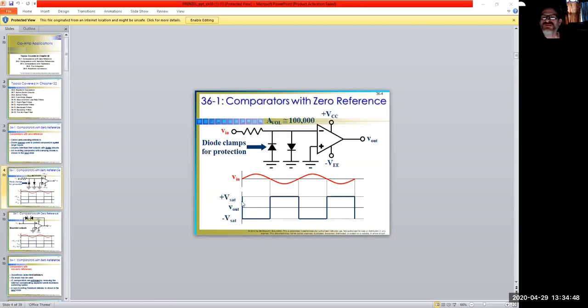So how is this device? Basically, by not having feedback loops in here or anything like that, we're running this thing wide open. So what becomes our limitations? Well, our limitations are literally, in this case, the VCC and VEE. That would be if I pushed a signal large enough to come through, the limitations would become both of the sources right here.